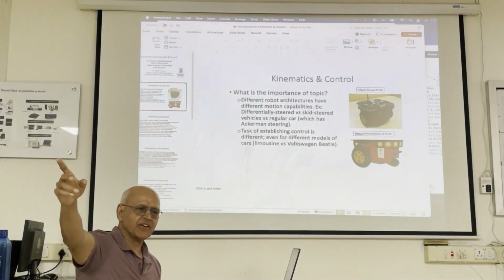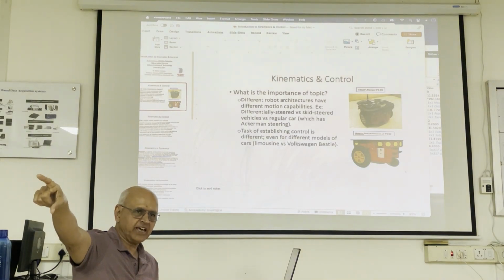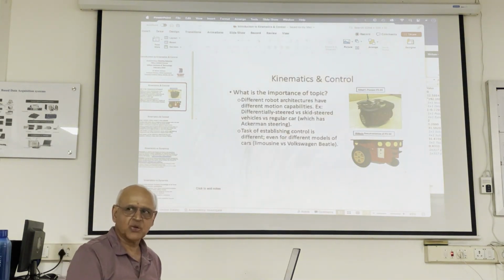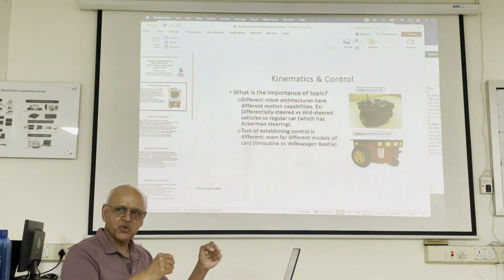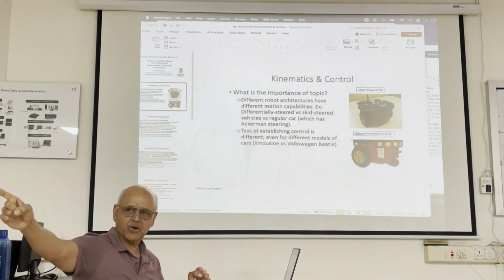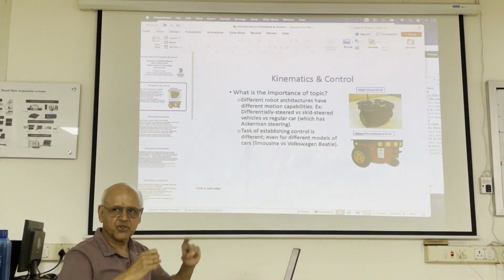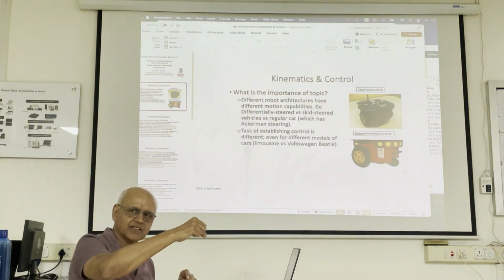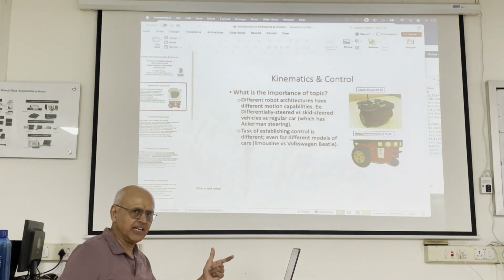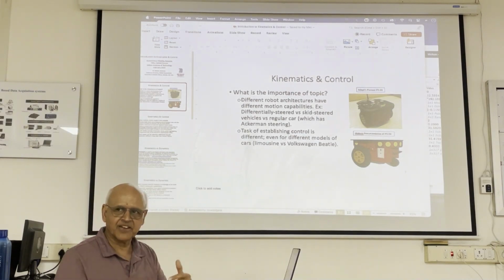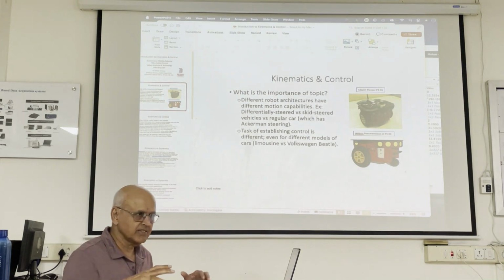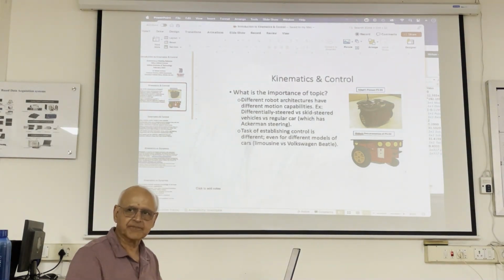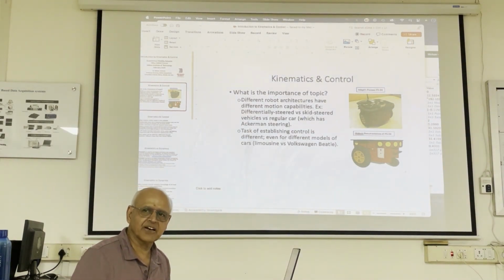So that has caster wheels. This is the old wheelchair, which they don't make anymore because they've gone to a driven form of the wheelchair, in the sense that now you steer the wheelchair. This one is a differentially steered vehicle, so you need to have a joystick. If you go like this, you're making the right wheels go faster than the left wheel. If you go like this on the joystick, the other way around. So you steer it using a joystick. Now they have wheelchairs that are steered just like a regular car, with a handlebar.